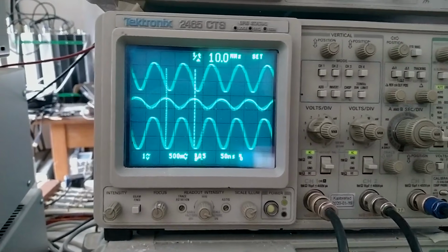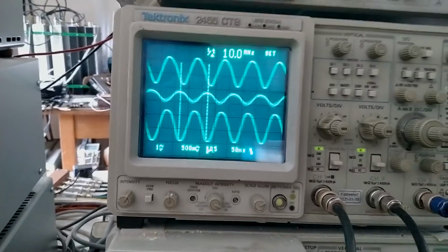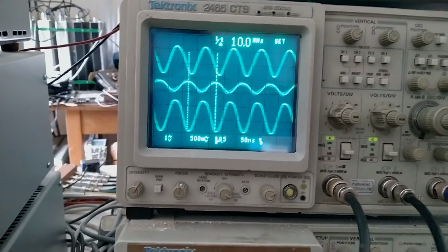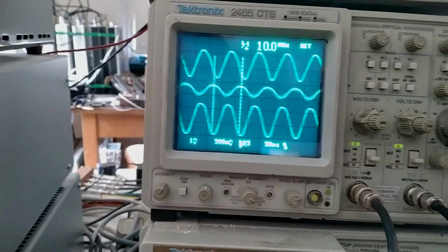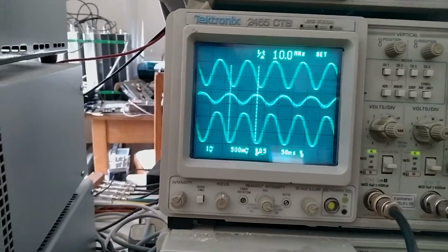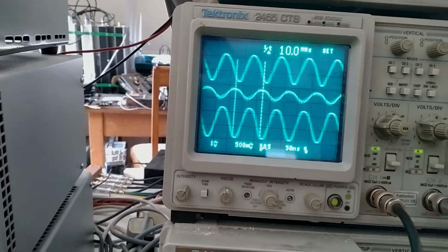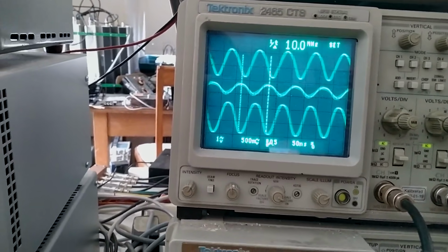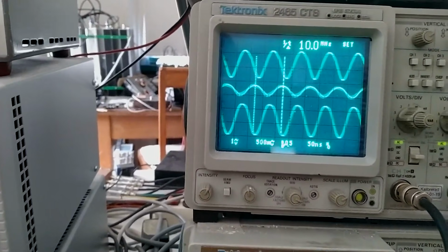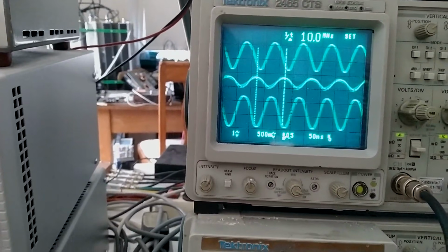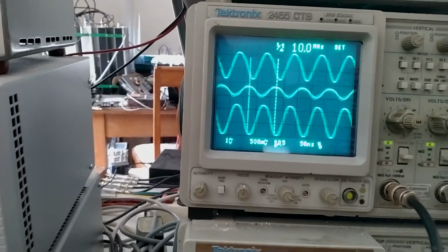This is helpful when setting the frequencies correct for the phase locking. The lock range is small, so it has to be set reasonably accurately. The upper trace is the oscillator in channel number 1. The lower trace is the oscillator in channel number 2. And the trace at the center, which I am using to trigger the oscilloscope, that is the frequency shifted rubidium source.